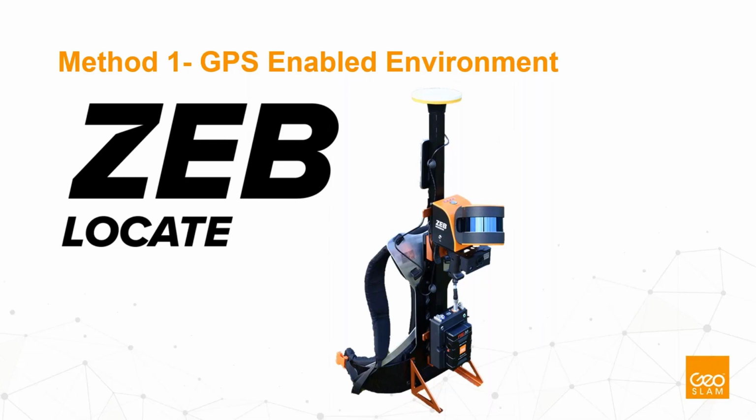What's very handy about this product is it's very, very simple to use. There's no need for massive calculations of lever arms because it's a set offset there. When we start the scanner, it's completely independent from the GPS. What it does is it marries up the two trajectories, one from the GPS and one from the scanner, and that's how it basically georeferences the data. So that's a nice simple way of getting GPS enabled point clouds straight into whatever data framework you have.